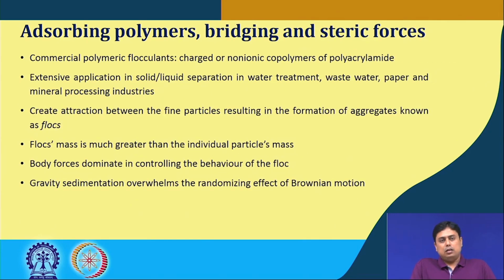The other aspect is that when used commercially, these polymer flocculants are typically charged or non-ionic copolymers of polyacrylate. They have extensive applications in liquid-solid separation, water treatment, wastewater treatment, paper and mineral processing industries. What it does is create attraction between the fine particles that results in the formation of aggregates, also known as flocs, from flocculation.